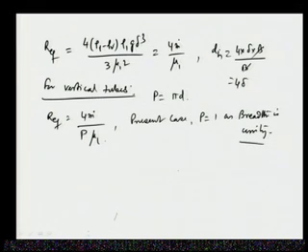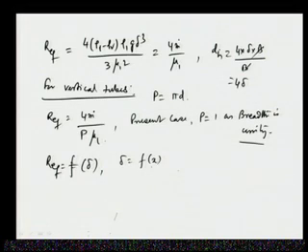Now, once we have got the expressions for Reynolds number, we can find out that Reynolds number is a function of delta, and delta is a function of x, that is the distance from the top of the falling film over the plate. So, delta is a function of x and Reynolds number is a function of delta.